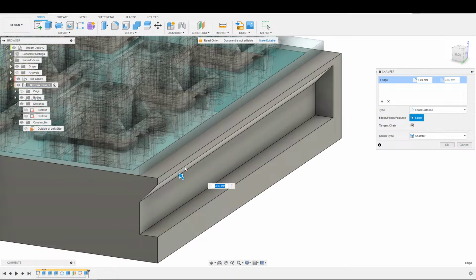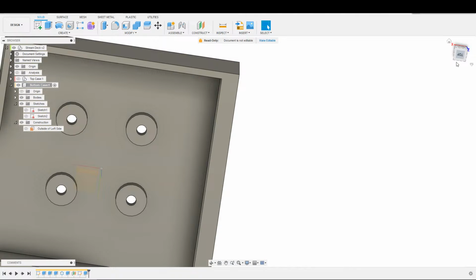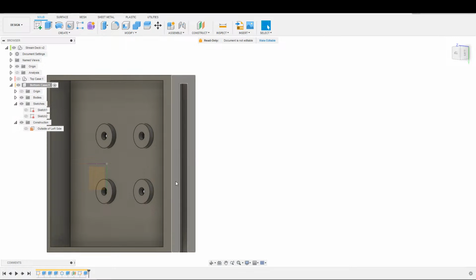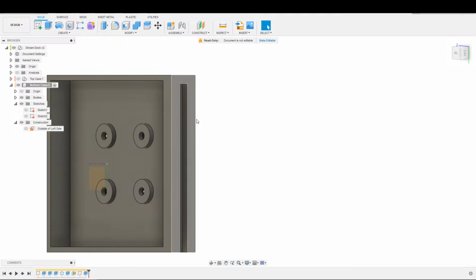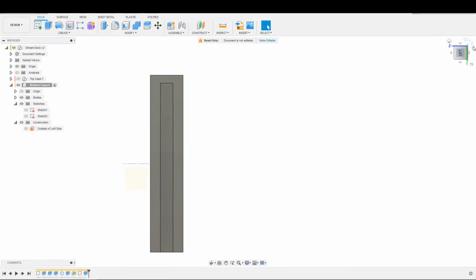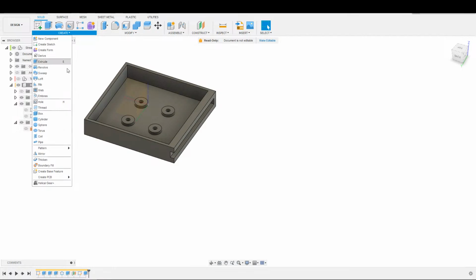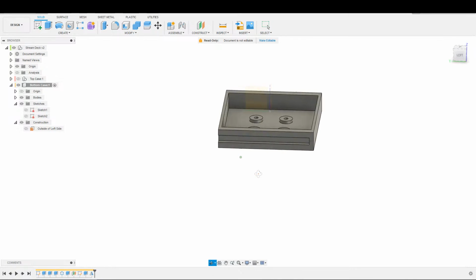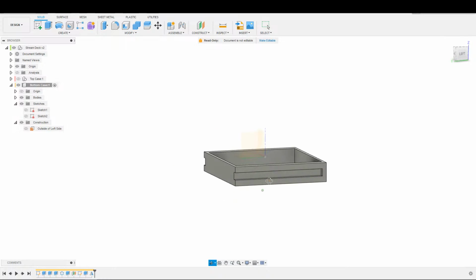The reason why we would need to include supports in this overhang is because our only other option is to print it standing up on edge like this. If we printed it standing up on edge like this, I meant to go to the other edge. There we go. Now we don't need supports in here. However, we do need supports all the way across here. So that is obviously a lot more support material across here than it is over here, printing it on the side like this. So printing it on the side like this is the only supports we need, obviously mirrored across the other side. And unfortunately, that's what we're at because our alternatives are inferior. They create more problems than they solve. So there is that. There are slides now that we're stuck with, unfortunately, because we do not have any other options. The next thing I want to do,